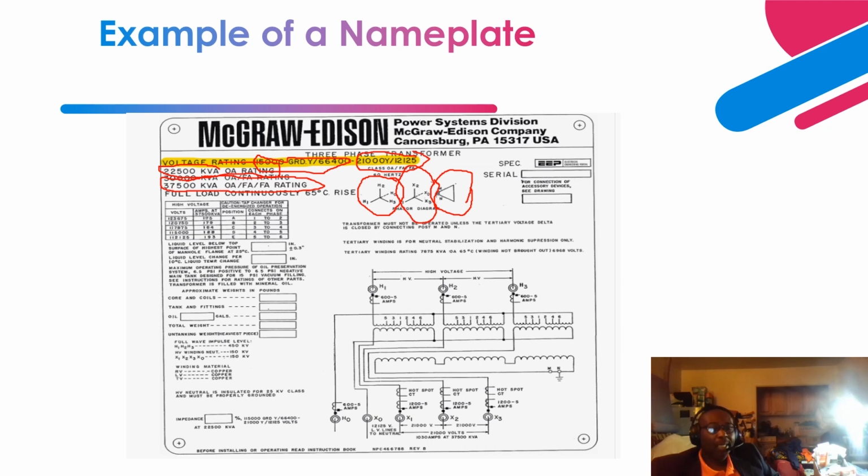So at this stage, you have two-stage cooling fans that come on. The first stage cooling fans is on. The second stage cooling fans is on. So you have all this forced air that is blowing across the surface of the radiator to remove all the heat to make sure that the transformer is able to achieve the oil temperature rise above ambient.